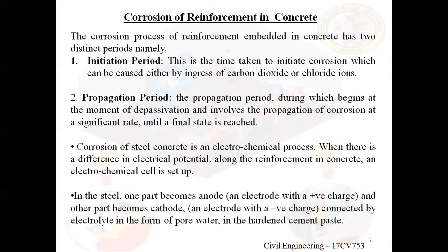That should be more. What happens if the initiation period is more? The corrosion initiation will be late, so we are on the safer side. That means if the initiation period is more, the carbon dioxide and chloride ions will take longer to reach the steel.